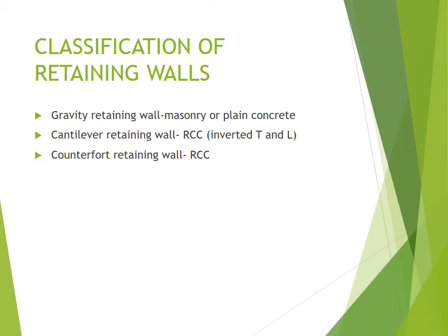According to the drawing, you can see how the reinforcement is done in cantilever retaining walls, whereby you also have hardcore behind the weep hole, which is 75 millimeters diameter. This weep hole is used to drain water from the back soil back to maybe the other side or the ocean, sea, like that.